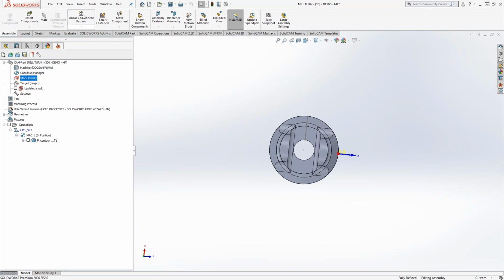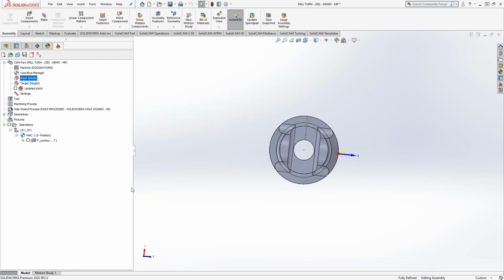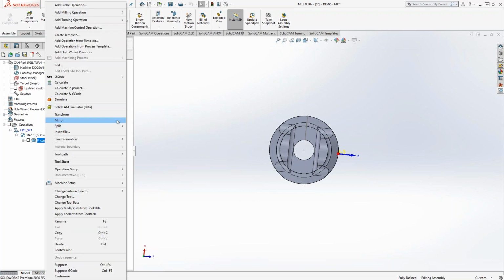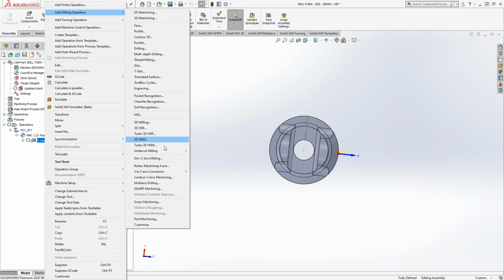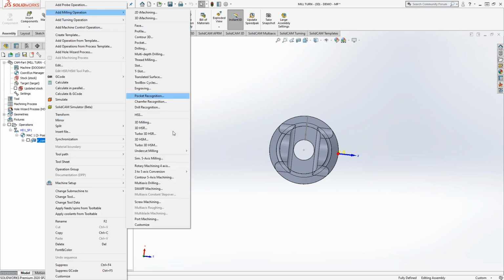Absolutely. And you'll notice that customized menu, which I think we introduced very recently, is pretty much at the bottom of every one of our menus now. So if you tend to skip over a lot of this stuff, or let's say in your toolpath list over here you don't have some of these, you can go to customize, and then you can uncheck the box next to the names of all the toolpaths that you don't have, and that way your list gets really shrunk.